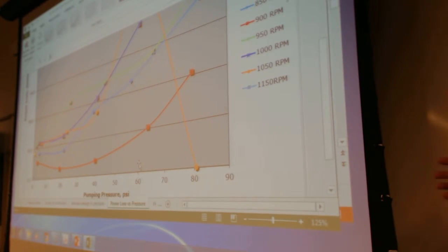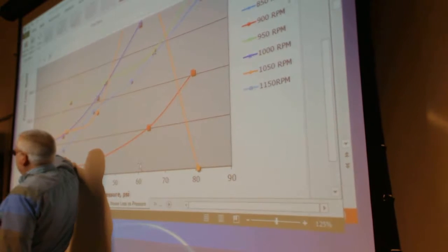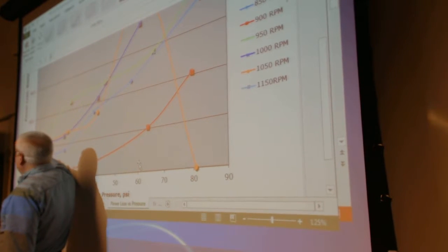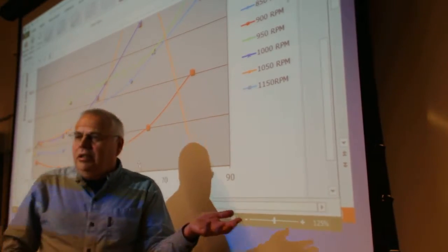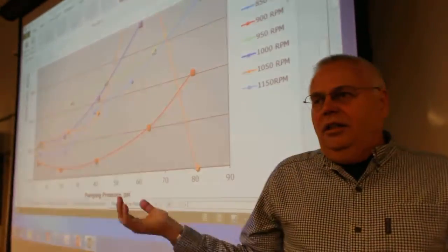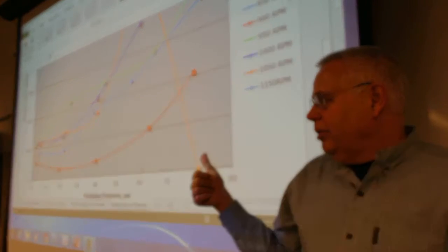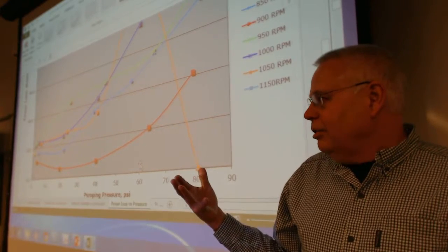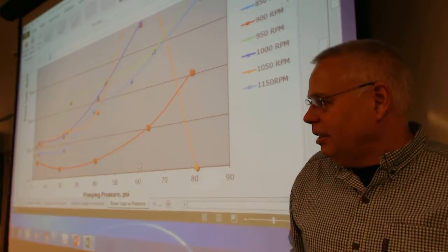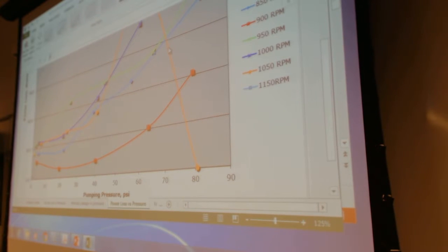When you come down to the point where there's no back pressure and essentially no leakage, this is basically the leak flow rate thing. You can come down to a point where you say, I'm losing that much power, and it's not because of leakage. It must be because of just the friction of the air motor, whatever couplings, misalignments, and internal friction, all that stuff bundled together. It just takes that much power to turn the pump system.